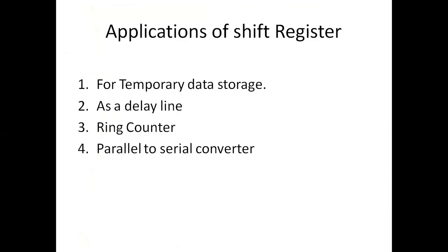So what are the applications of a shift register? For temporary storing of data, you can use the shift register as a delay line, because one flip flop gives a particular delay of one clock pulse. So we can use a register as a delay line. We can design one special type of counter using the shift register. After this slide, we will discuss this one. And obviously, we can use the shift register as a parallel to serial and serial to parallel converter.